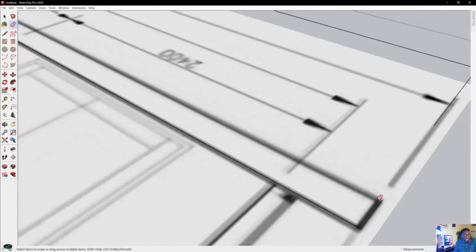Now you want to ensure that your lines actually snap. So notice that my line snapped to the green axis there, and once I do that, you will see it infills. Now once it's infilled, that means that your line is flat and accurate. Well, for the most part. Sometimes it's not. But you want to ensure that that is accurate. So I'm not eyeballing to get this measurement because I actually have the measurement.